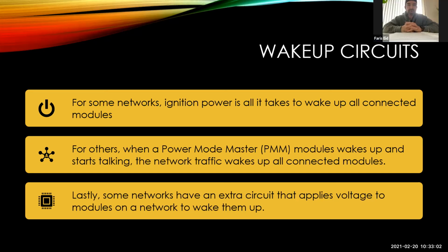Good question. So if there's an issue with that power wire, then that could also be a communication problem. Right. So if I have a network that uses an external wake up, even if I have power to the module and I have network communication to the module, it's never going to talk because it was never woken up. So we need to know the way the network's configured, just specifically for that reason.